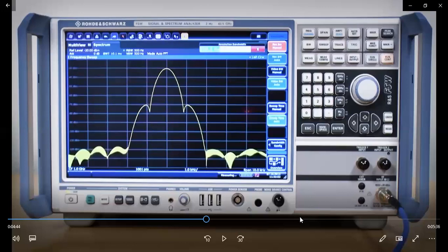But for the power level detection, your resolution is now wider. Over 30 kilohertz, you are determining how much the average power level is over this whole range of frequencies. So the granularity in the frequency domain is now poorer. For every 30 kilohertz, you get an estimation of the power levels. Previously, you had that for every 3 kilohertz.